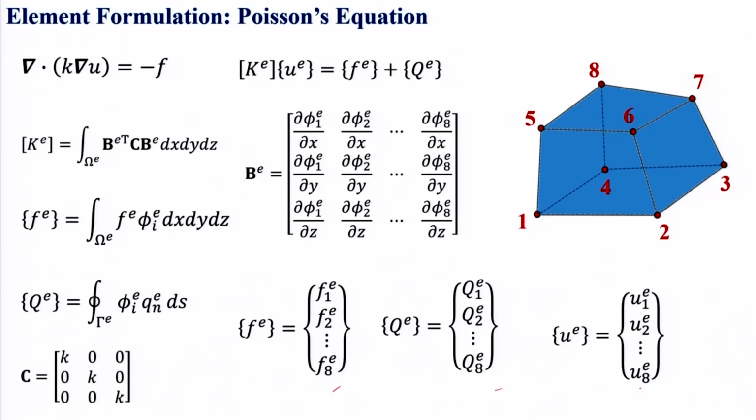Again I repeat, in order to calculate the boundary flux term, this boundary integral, if you recall, in the case of a 2-dimensional problem, the boundary integral needed to be performed on the boundary which coincides with the natural boundary conditions, right? The case is the same even in a 3-dimensional problem. Only now the boundaries of the elements are the surfaces, right? So this integration needs to be performed on the boundary which coincides with the natural boundary.